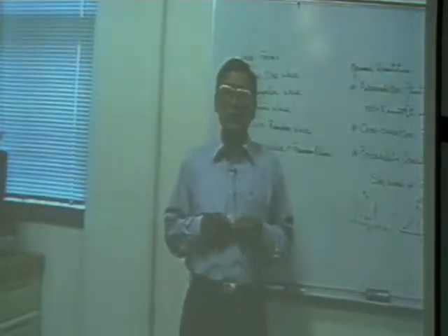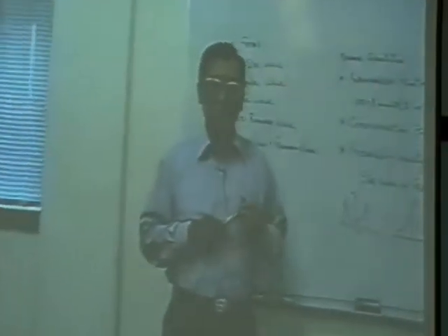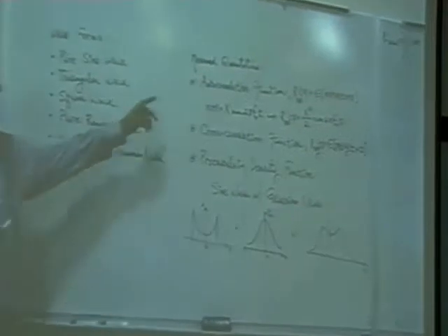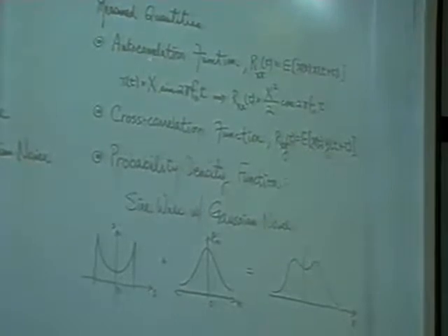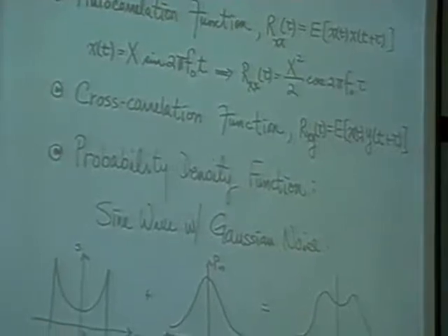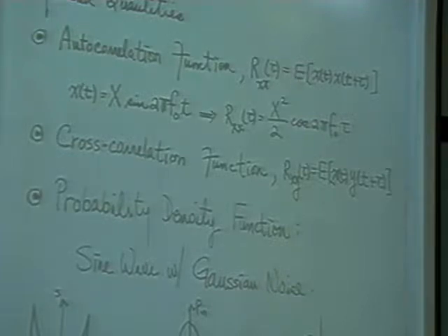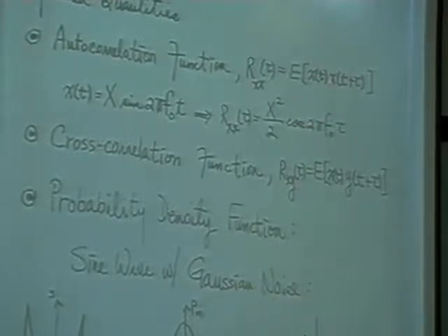Okay, and what we're going to do in the first experiment. So first experiment, I put it down. You're going to do this, okay? Here. We are going to measure the autocorrelation function. So it's zooming in. This autocorrelation function, as you learn, which is R xx tau, is the mean of x(t) multiplied by x(t + tau).